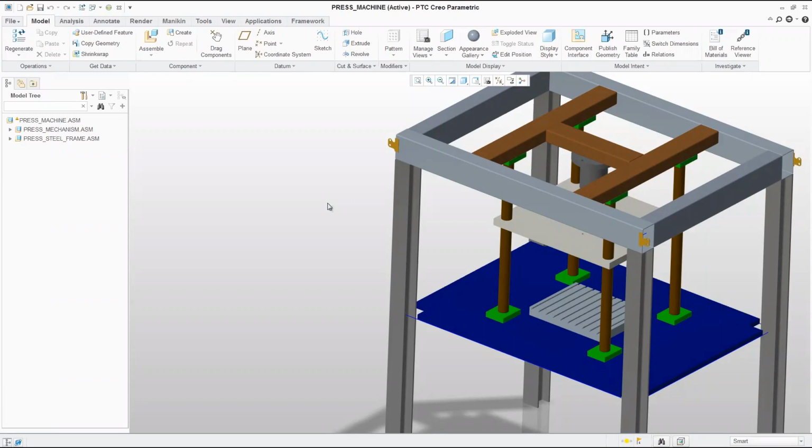Bill, you might have more experience with this one. Short answer is yes, it works. The Simulate program does not require a model tree. It is going to operate on whatever geometry it sees, so imported geometry can be run just fine. The only problem you would have is that what Zach just showed you with the parametric optimization is not going to be so easy, because you don't have dimensions in a model tree to vary.